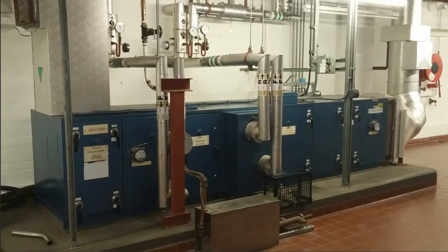Now, to open up the AHU, you're going to need to open some of the panels up, the access panels, which are purposely there for that exact reason, so you can climb inside and have a look or fix or change the filters, change the belts, etc. So on the AHUs, on the panels you can access, you'll see these handles here. You might have handles, or it might just be a panel key fitting. In this instance, they've got the panel keys there, so you would undo these and just lift those off, and in this case you would just turn these and that will undo the hook, and that will allow the entire panel to come off.